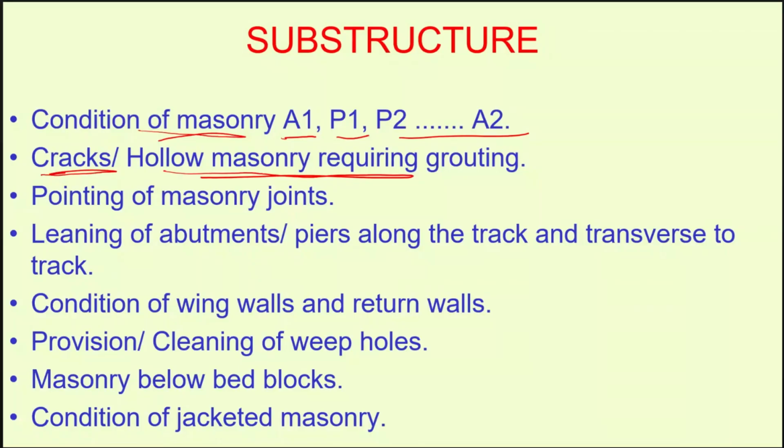Similarly, if there is hollowness, you put a rubber pad and hammer it, and you will be able to see what type of sound is coming out. If the sound is very dull, that means the structure is hollow behind, and then you need to do some sort of filling of that hollowness.